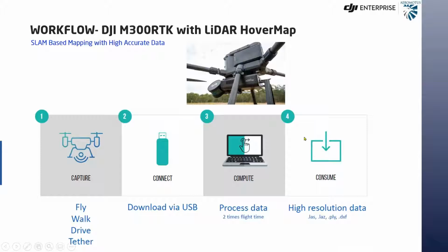The workflow on the LiDAR OverMap would be, as I said, it can be used in different environments. You can even do handheld scanning inside indoor environments. You can fly, walk, drive, and tether. Then download the data. There's a pre-processing software which comes along with the payload, taking almost 2 times the flight time. It is able to give you high resolution outputs in LAS, LAZ, DXF, and PLY format.